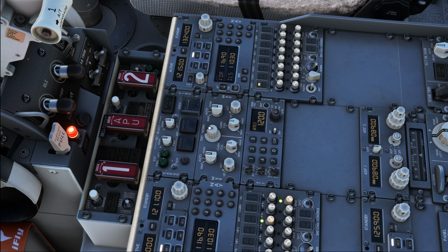There are a couple of pilots, some rumors say, that would leave them on the test position when they leave the aircraft, and when you do that, when the switch is over here, apart from the rumor, by the way, it's normally the maintenance personnel that just forgets it there after running the maintenance test. Remember, as pilot, you don't have to do that test. So when the switch is over here and you activate the weather radar when lining up on the runway, you're pretty soon gonna get a wind shear warning, so be sure that that switch is in the norm position. Moving further down, the gain is set to the calibrated position, and that applies to both sides.